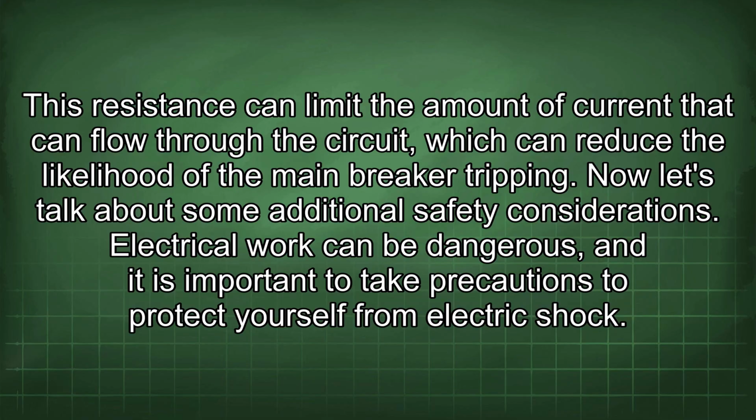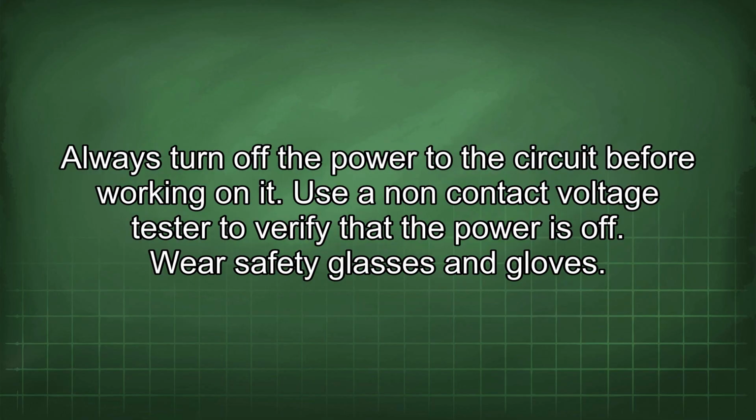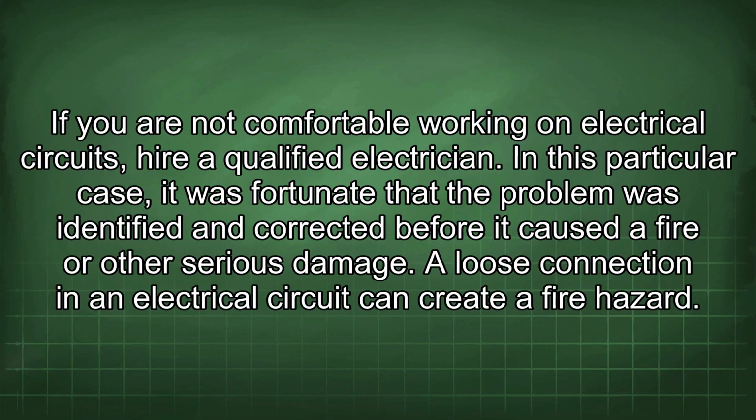the main breaker tripping. Now let's talk about some additional safety considerations. Electrical work can be dangerous, and it is important to take precautions to protect yourself from electric shock. Always turn off the power to the circuit before working on it. Use a non-contact voltage tester to verify that the power is off. Wear safety glasses and gloves. If you are not comfortable working on electrical circuits, hire a qualified electrician.